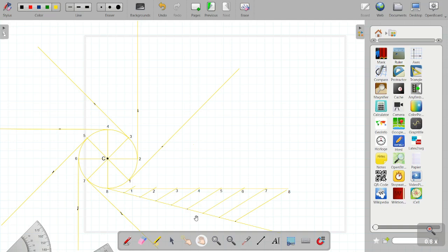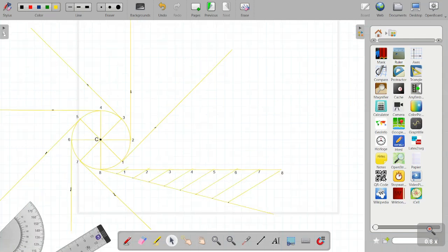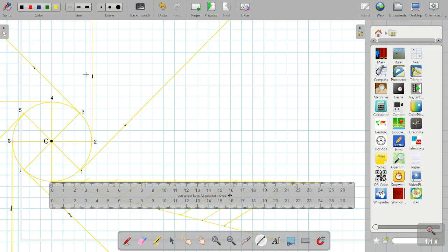In the second problem, the length of the string was given as 180, so we constructed the involute accordingly. And now in this particular question, we are given that the length of the string will be 240. So first what I need to do is mark 240 and I will name this point of 240 as point P.